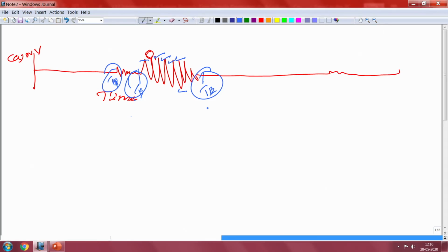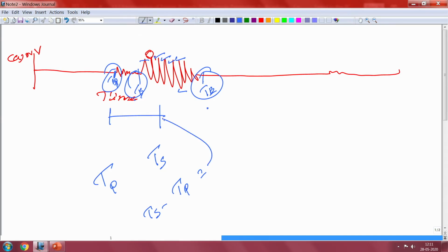So, basically you can get Tp, which you obtain from this point. The other one is the Ts. The difference between the Ts and Tp will give you this distance. This indicates how far your seismic recording station is from the earthquake. This will be equal to Ts minus Tp, which you convert in degrees to your distance.